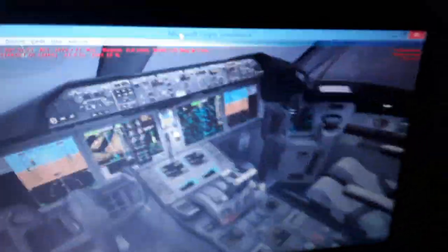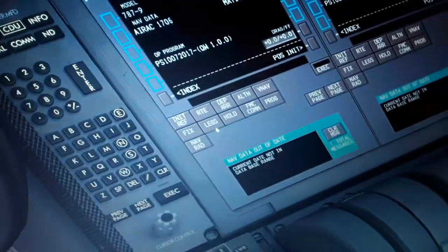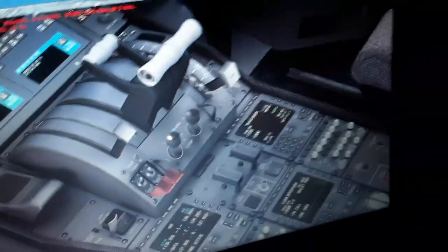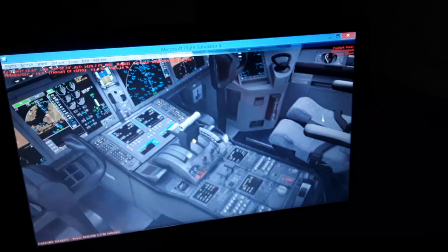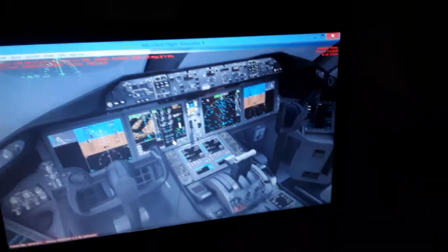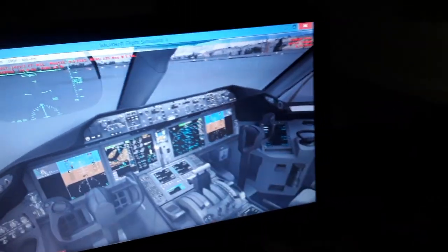Also the screen here, you will see the keyboard. I will use the values, the alphanumeric values, and select the modes we need to set up the flight management computer. Have also the mouse pad here. You can see the thrust levers. I can move forward enough over here using the thrust levers control. You can set the percentage of the thrust needed for flying the aircraft. So you will see we increase the thrust up to a takeoff go round mode.